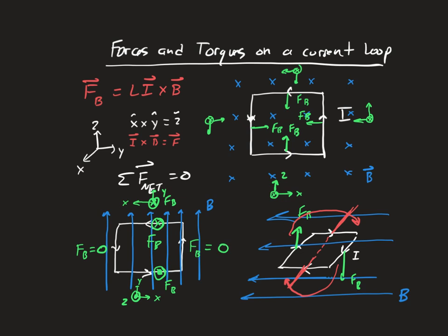Now, what's kind of tricky is when this thing spins halfway, meaning the loop is now oriented like that in the magnetic field, it's actually going to be in this situation. So we actually have to be a little tricky if we want our motors to continue to move, because they'll just flip into this position and be in static equilibrium, right? So we have to talk a little bit about how we actually get motors to move. We have to switch the current direction to get them to move past the equilibrium point, which we'll talk about. But this is the basics behind generators and motors: getting forces on opposite sides of loops to spin in the magnetic field.